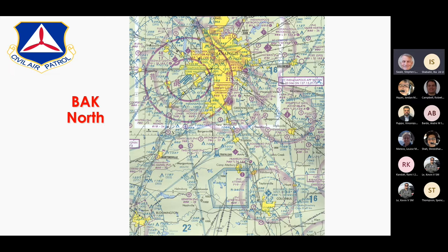If you have an electronic flight bag, like ForeFlight, you can just touch on this restricted area, and by following the prompts, you can get all the information of the restricted area, including the frequency to contact the controlling agency, times of operation, altitude, definition, etc.